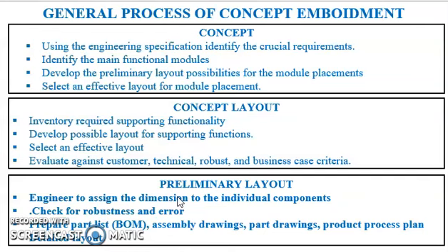In addition to this, the product should be evaluated for customer needs, robustness, safety and economic criteria. Now the developed layout should be checked to estimate potential faults, tolerances and clearances for product accuracy and repeatability. The embodiment process concludes with testing of a physical prototype.